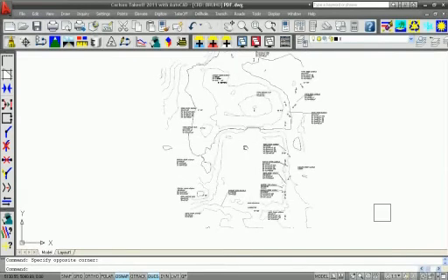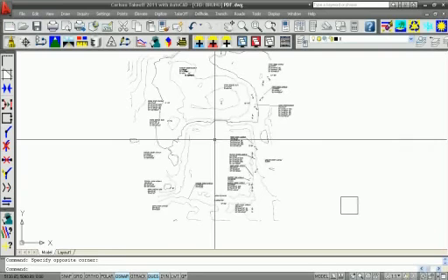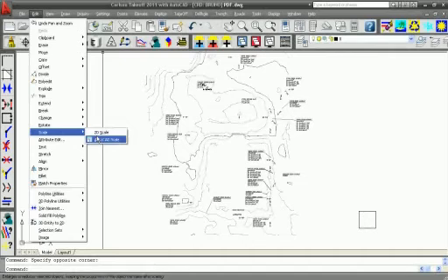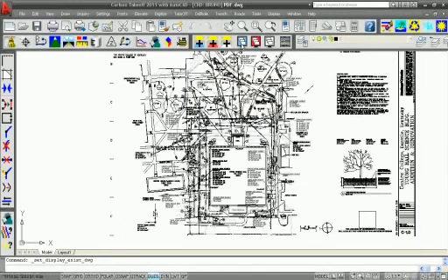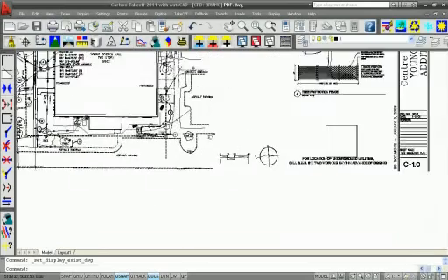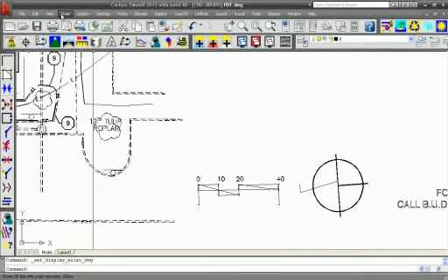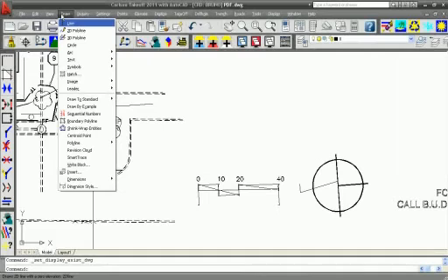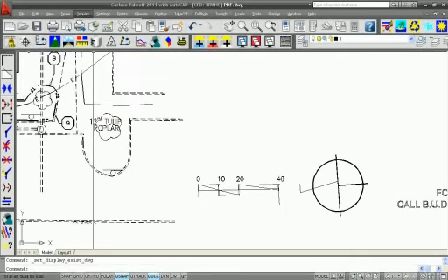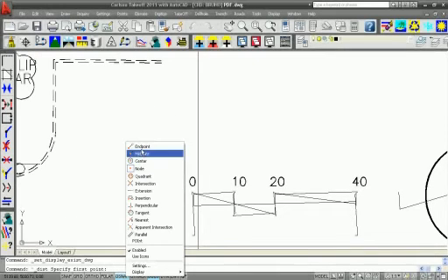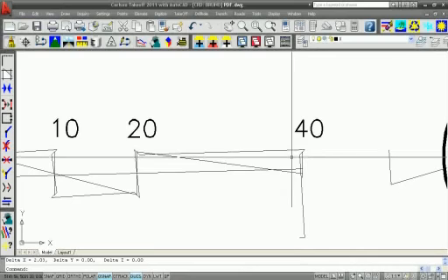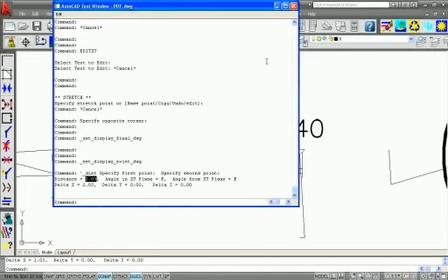One other helpful command now for the PDF is scaling it. The new scale that we have is under Edit, 2D Scale, and let me turn on the design right now. Okay, so right now in the drawing, the scale is off. Importing a PDF, your drawing is not going to be scaled accurately. If I do an inquiry, standard distance, and let's turn my O-snap on. So from 0 to 40, this should be 40 feet in the drawing. If I click here to here, and F2, that distance is a little more than 2 feet.